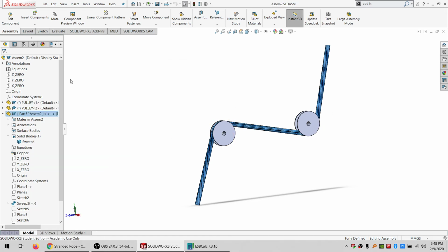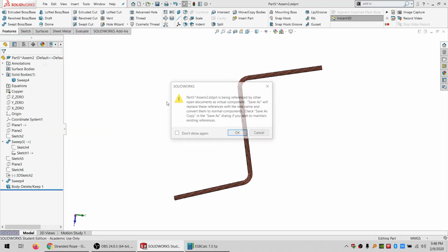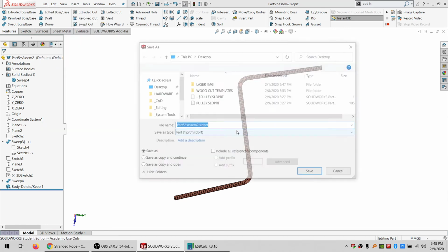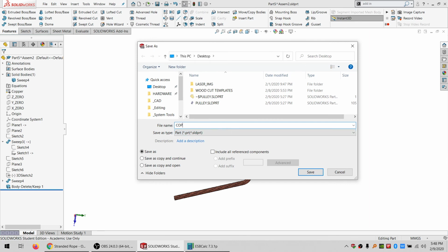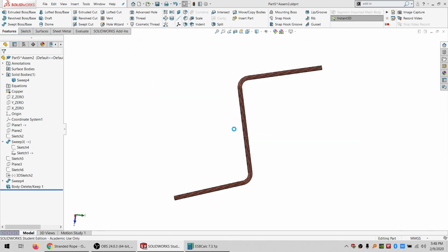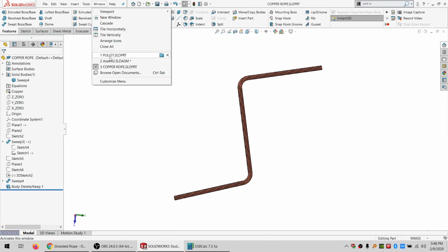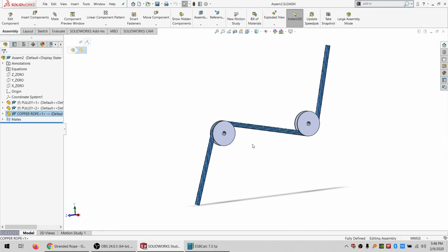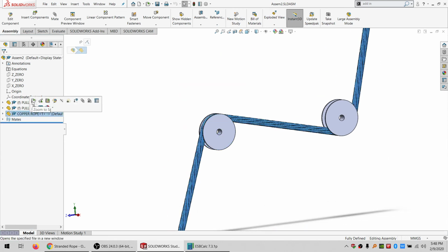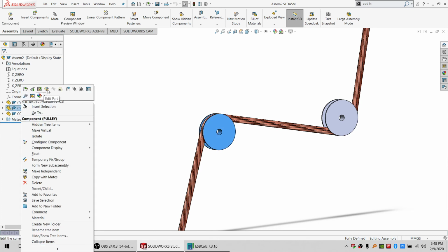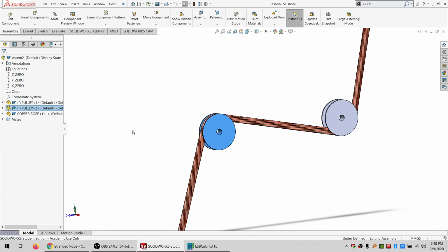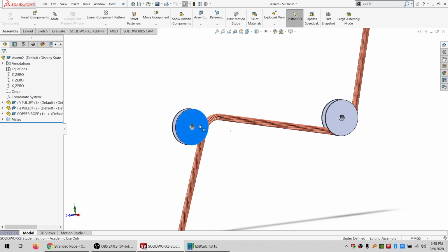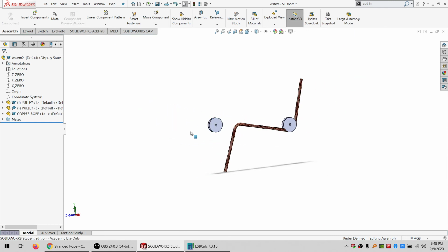What I can do is if I go back in here, you do File, Save As, and yep, it'll give me a little warning about what I'm doing. So then it's outside the assembly. Just go back to the assembly and save again so that it remembers that it's outside now. And then the cool thing is, let's float this and go over here. And I'm going to do Control Q, which is the force update everything command.